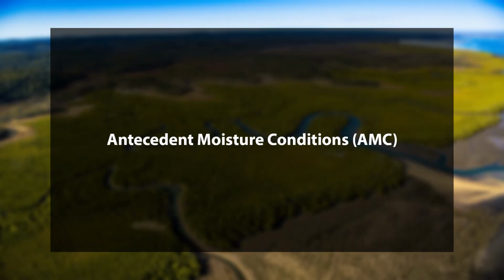In Indian conditions, there are wet and dry spells during which soils remain either fully saturated or dry. These conditions are called antecedent moisture conditions or AMC. The soil moisture data of these spells is a vital parameter in modeling the runoff and discharge in watersheds.